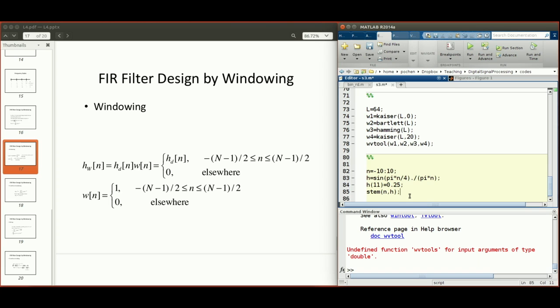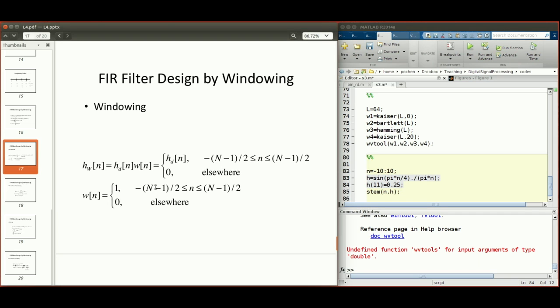So suppose we window it using a boxcar like this. W[n] is either equal to 1 or 0. Then for big N equals 11, the horizontal range for that window is exactly from... big N equals 21. So 21 subtract 1, that's 20, divided by 2, that's 10. So small n goes from -10 to +10 when big N equals 21, right?